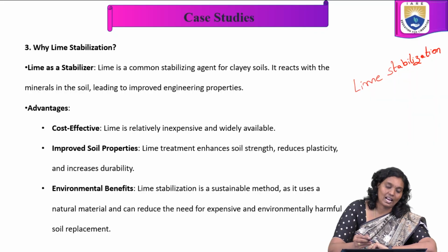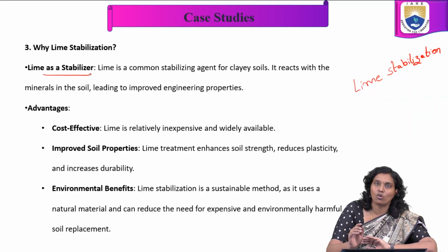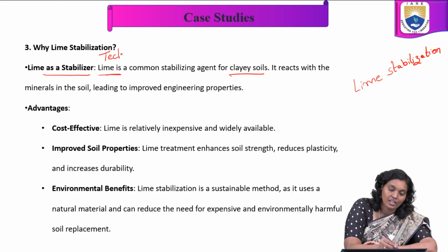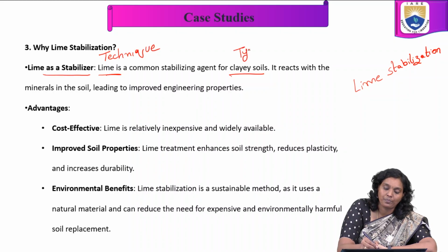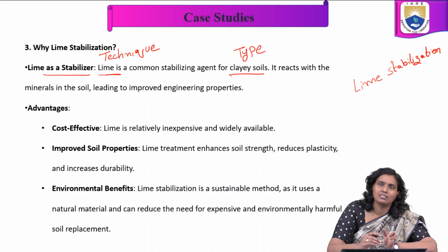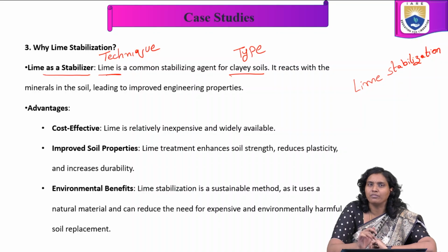Lime is a common stabilizing agent for the soil. Whenever we choose the technique, it depends upon the type of soil. Lime is suitable for clayey soil; other techniques suit other kinds of soil.